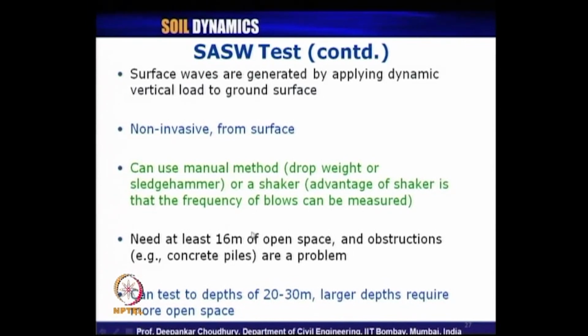Remember this point, because many times in the field you will find that contractors or field engineers are not following this criterion. In that case, you are not sure whether you are measuring a Rayleigh wave or some other wave, like even a body wave, because the time overlapping may occur. So, be sure to provide a minimum of 16 meters.